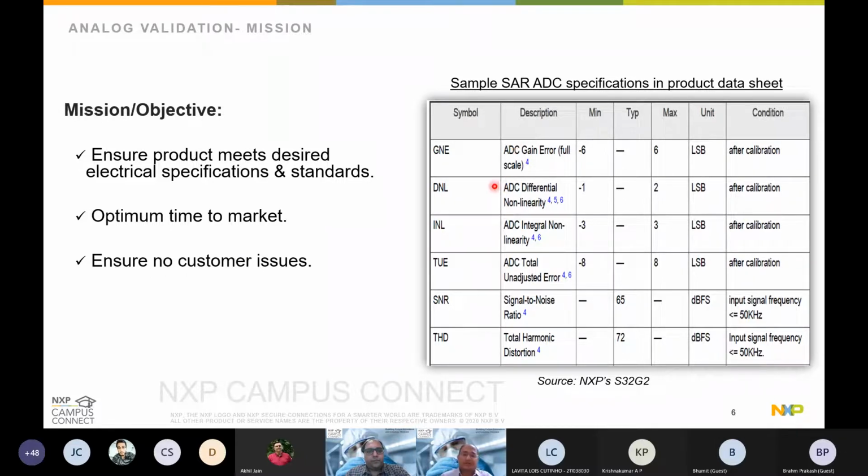So, how do we select parts from the market, silicon or any ICs from the market? The first thing is we have a certain spec in our mind. We know the use case where it needs to fit. Based on that, let's say, for example, 10 or 20 products are shortlisted. And then after that, I have to filter them and see what specs are really critical for my application, and then shortlist. And this is all done with reference to a product data sheet.